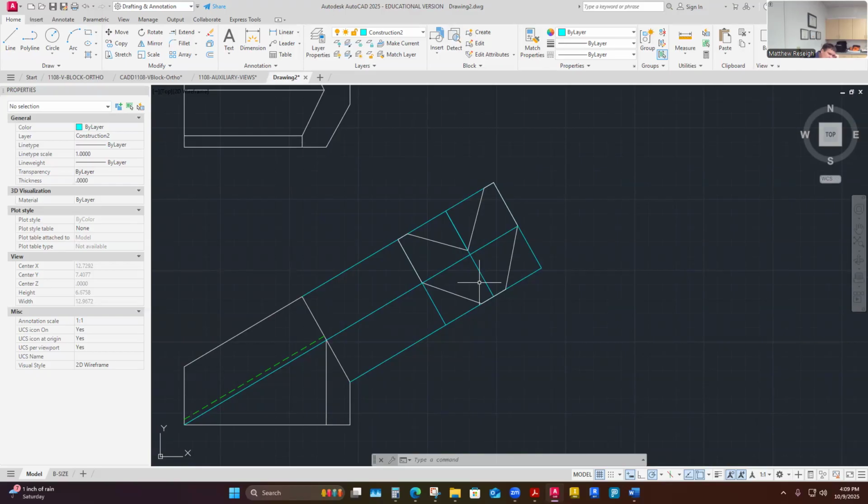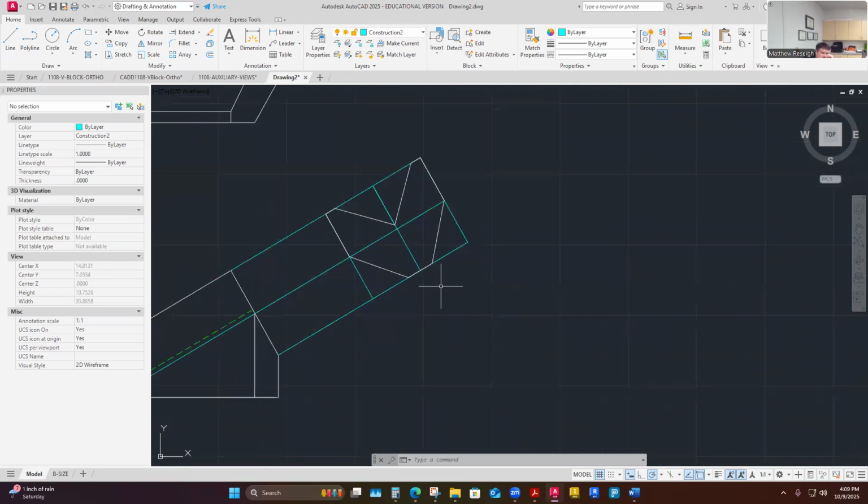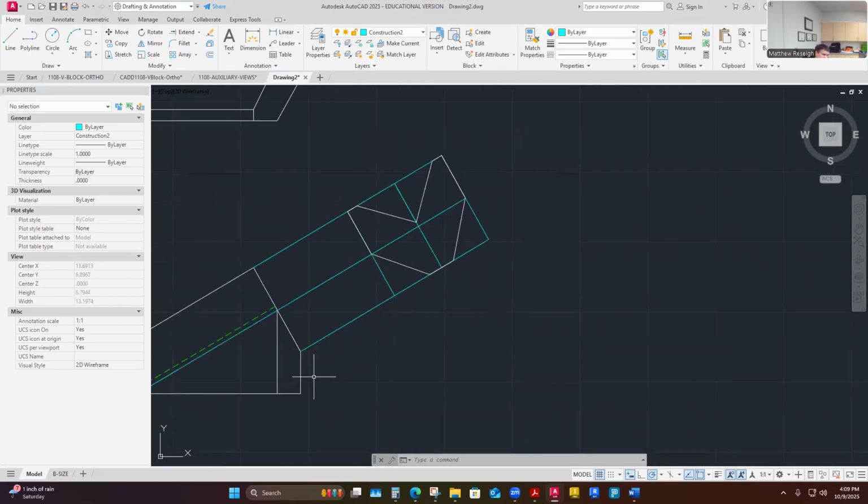It's going to pick up some foreshortened stuff that isn't helpful, but maybe it helps, like it'll just complete the view. So I'm doing a full auxiliary view, which just means I'm going to need to show this stuff here. I'm only displaying the surface that's in question right here, displaying it in its true form with its true lengths. But what I would also pick up is foreshortened stuff in this view that I'm going to be able to dimension in those other two views, front and top. So to draw that, it's just going to be like this surface I'm going to see.